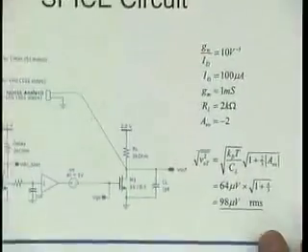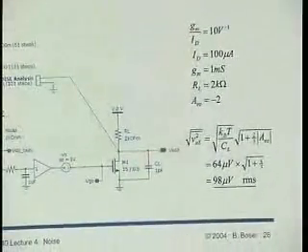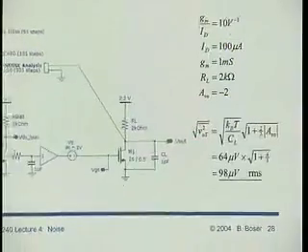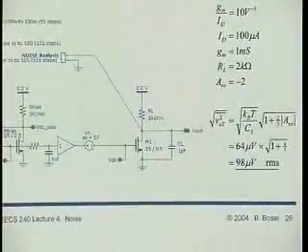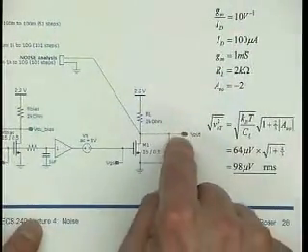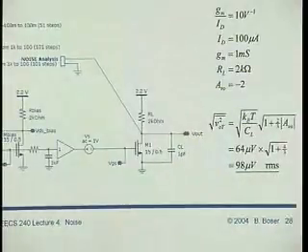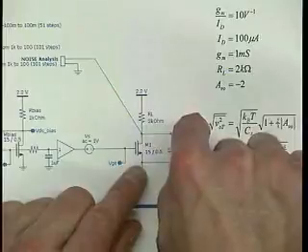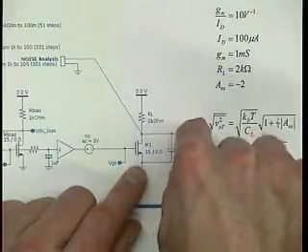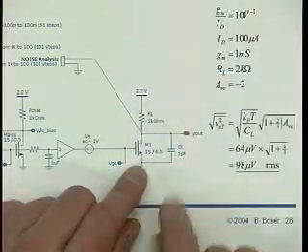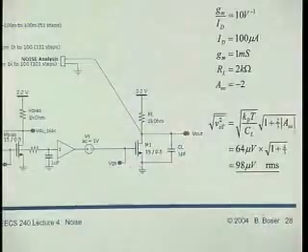Then, of course, after this, I immediately went back to our common source example, and now I calculate what is the total noise that comes out of this common source amplifier. At the output of my common source amplifier, I put the switch and the A to D converter and so on. So the CL is actually part of the A to D converter.